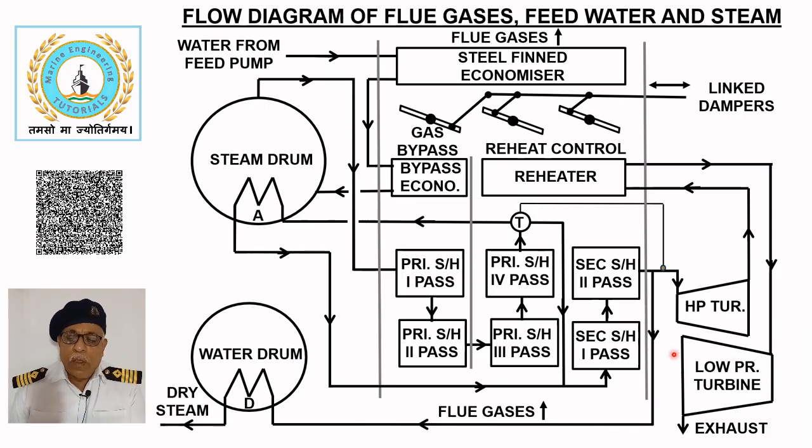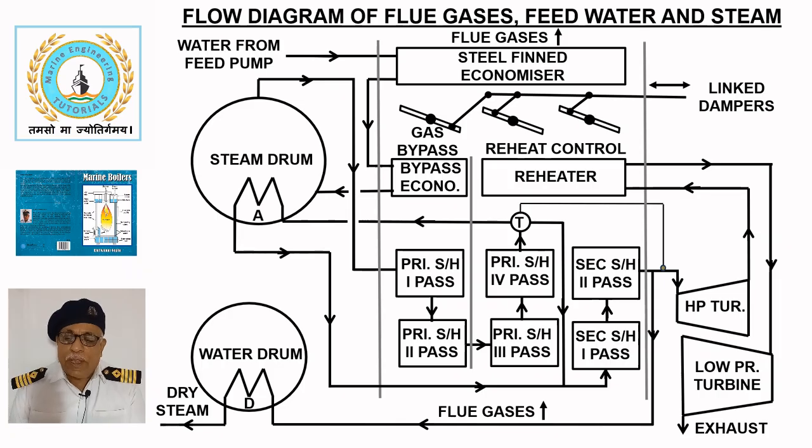Auxiliary steam for miscellaneous services is obtained by passing superheated steam through a desuperheater located in the water drum, producing nearly saturated steam. This boiler was capable of producing 68,000 kg per hour of steam at 45 bar and reheating the steam from 322 degrees Celsius to 454 degrees Celsius.